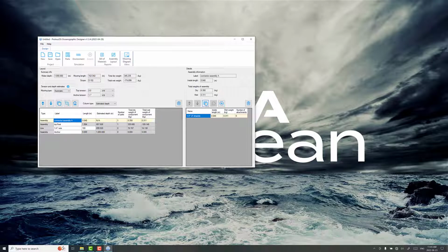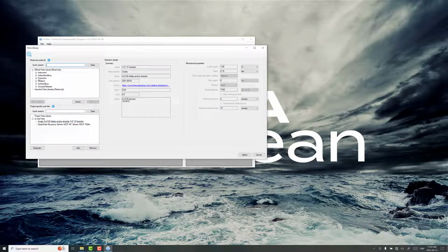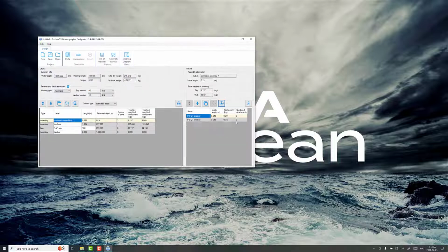This makes it really nice and quick to put things together, and it really helps with mooring assembly if you have a sling link in between them. So use a weld with a sling link, 5/8 with the same working load limit. And just make sure that's in between the shackles there. And I'm going to move this down in between the top float and the wire. And we'll duplicate that here.